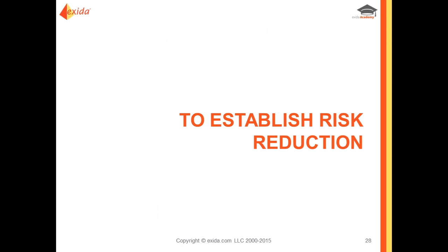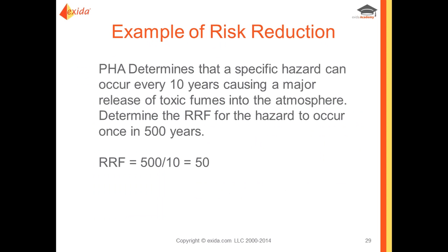But first, we're going to dive down a little deeper into safety integrity level itself and find out how it's used, why you need it. So the safety integrity level can be used in 4 ways: to establish risk reduction requirements, to look at probabilistic limits for hardware random failures, to look at architectural constraints. We just talked about that a little bit to find your SIL level, or if you have a SIL requirement that you already know you need, you can establish your architectural constraints.